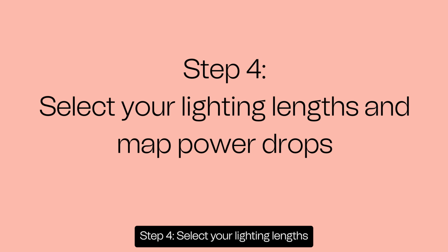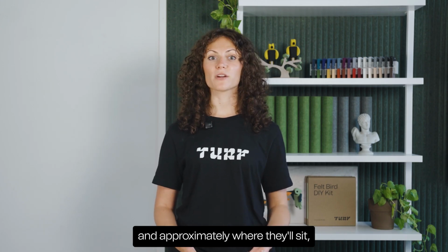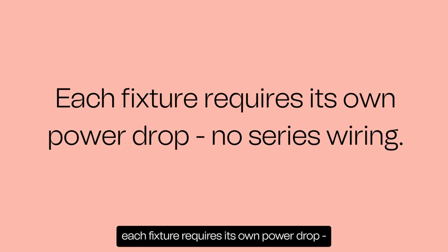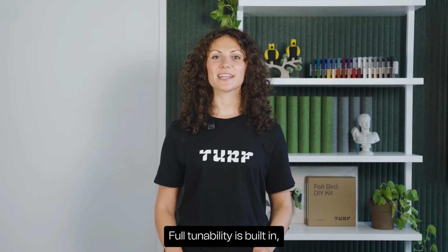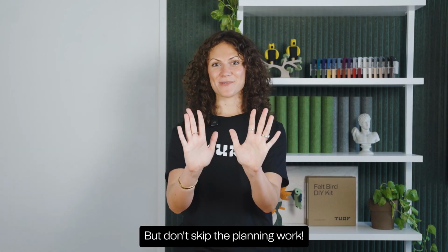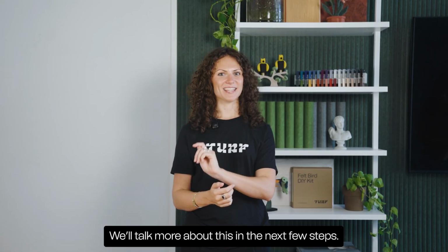Step 4. Select your lighting lengths and map power drops. Now that you know which rows are getting Beam LED lighting and approximately where they'll sit, lock in your fixture lengths using the standard product sizes chart in the cut sheet. Remember, each fixture requires its own power drop, no series wiring. Full tunability is built in, giving you a complete range of brightness and color temperature right out of the box. But don't skip the planning work. Map out your preferred settings based on how the environment will actually be used throughout the day. We'll talk more about this in the next few steps.